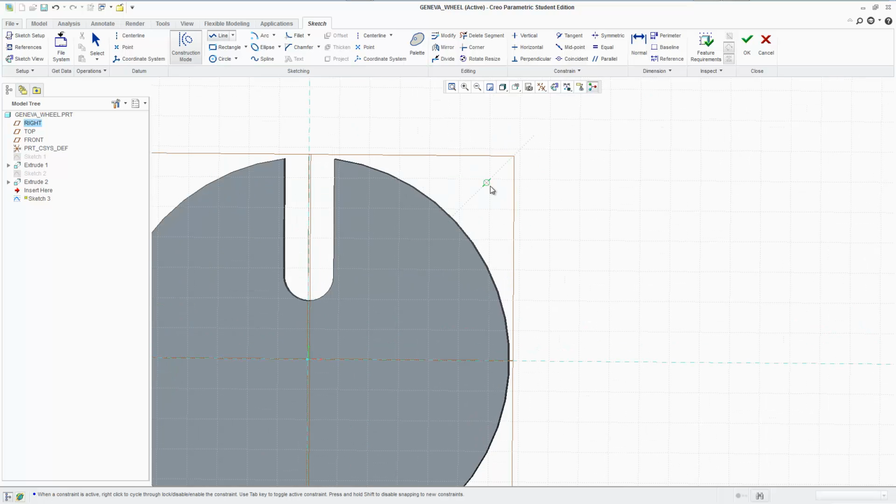But now I'm going to try to control the dimensions here. It already gave me some dimensions and some angles, but if you go up top at the dimensions where it says normal, click that, select the line, and then middle mouse button click right there. You can control the size. My calculated size for center to center distance is 5.65685. Yours might be different, it's fine. And it says 5.66.